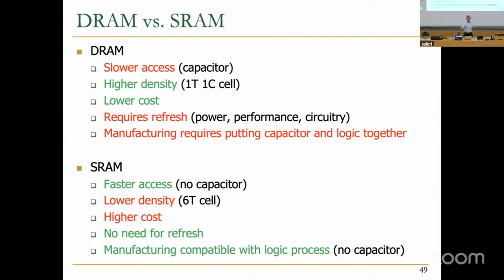As a result, all big memories today are DRAM. If you want storage, it's going to be flash memory, which I'm not going to talk about, but I will mention that later on. The downsides, the green ones are good, the red ones are bad, basically. It requires refresh. Refresh is not good because it consumes power, it leads to performance issues, and also it has extra circuitry.